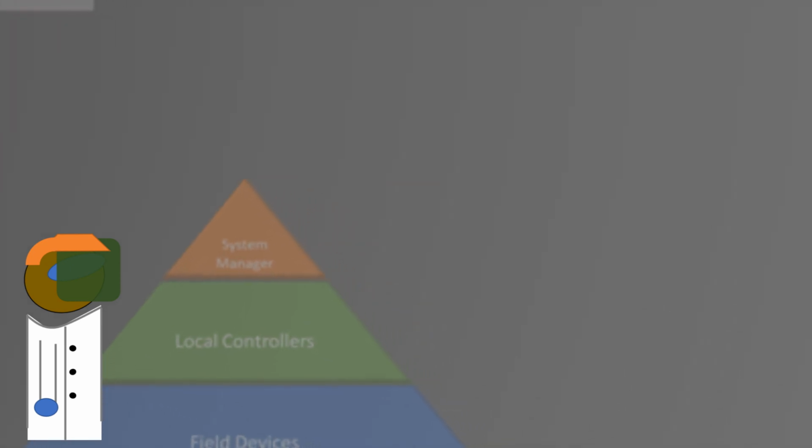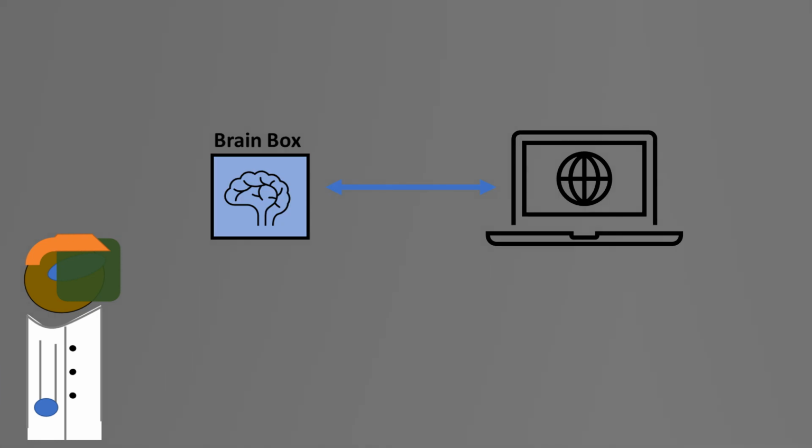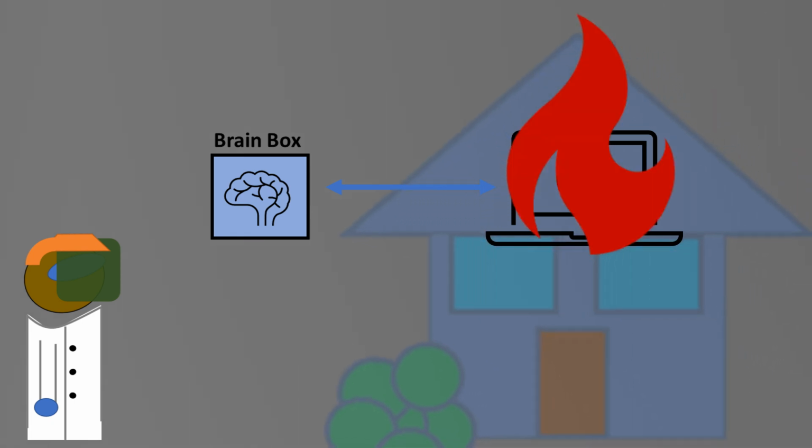But if you were unfortunate enough to not understand that you were not looking at an Ethernet port, you could plug in your laptop, and I believe the voltage on the Allen Bradley side was considerably higher, and so it was your laptop port that would be, in all likelihood, well, destroyed. So yeah, don't plug into that.